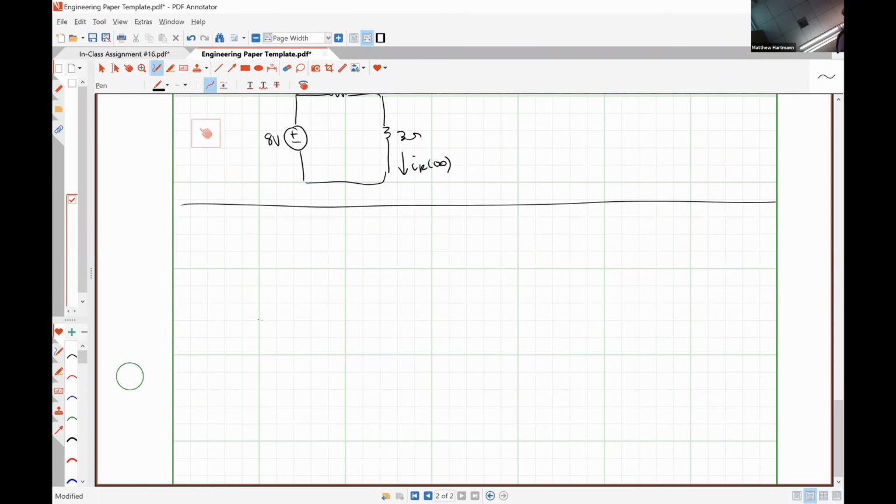So it's very important that we turn off our current sources and our voltage sources. My off current source looks like an open circuit. Here is my 5 ohm resistor. Then I'm going to have effectively an open circuit here. Here's where my voltage source was switched on, but I need it to be off, so I'm going to short it out. So there's my shorted out voltage source. Here is my 10 ohm resistor. Here's my 3 ohm resistor.